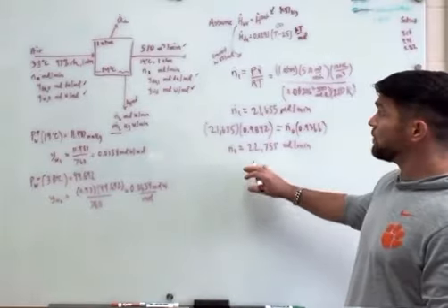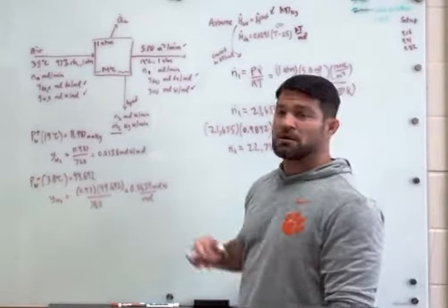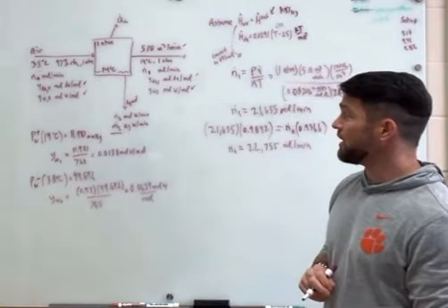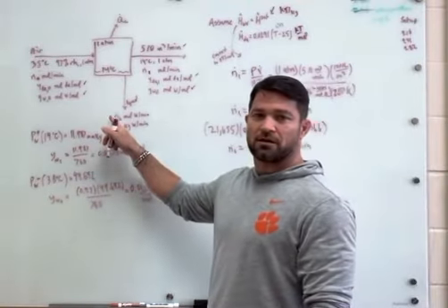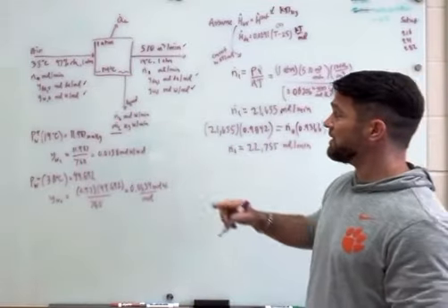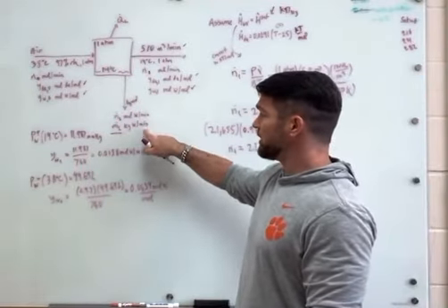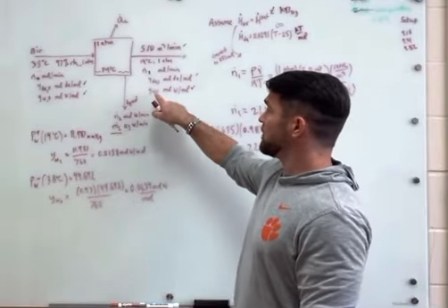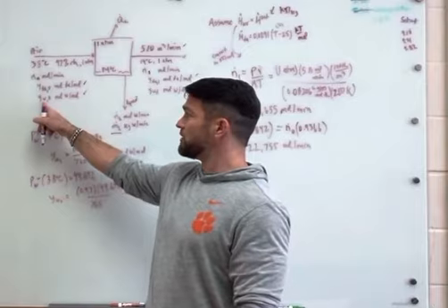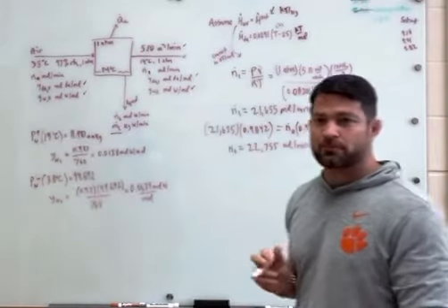Okay, so what else do I need? Now I need to know the total moles of the liquid water coming out. To get that, I can just do a water balance on this process. So I have the moles of water here plus YW times N1 equals YW0 times N0, right?